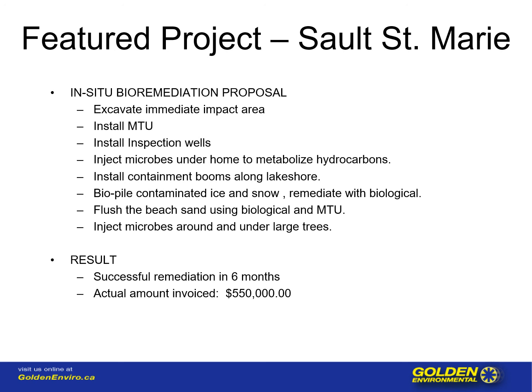We injected microbes under the home to metabolize the hydrocarbons. Then we installed containment booms along the lake shore to stop any further migration of the oil into the lake. After that, we biopiled the contaminated ice and the snow. We remediated this with a biological agent, the hydrocarbon digesting microbes. We flushed the beach sand using the biological amendment, the BIM 200, and using the mobile treatment unit. Then we injected microbes around and under the large trees in the area to ensure their survival.